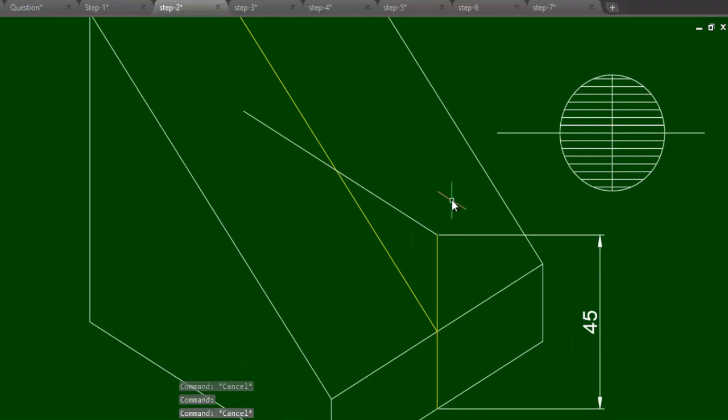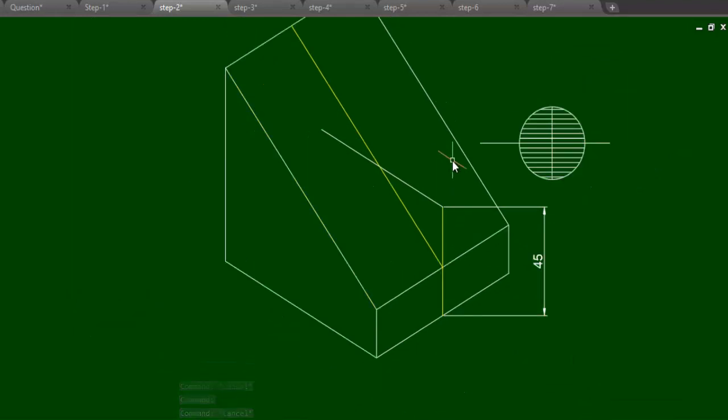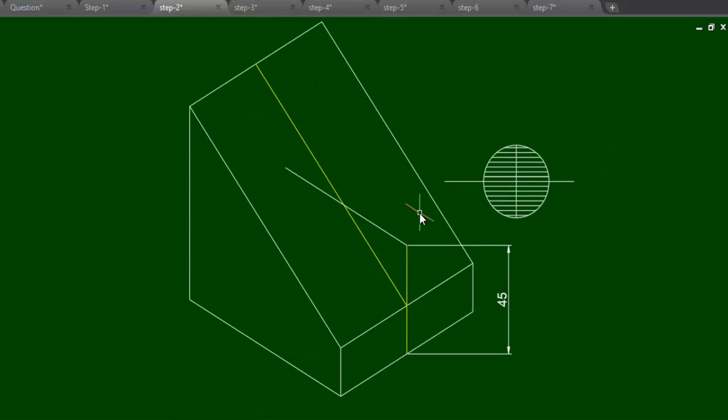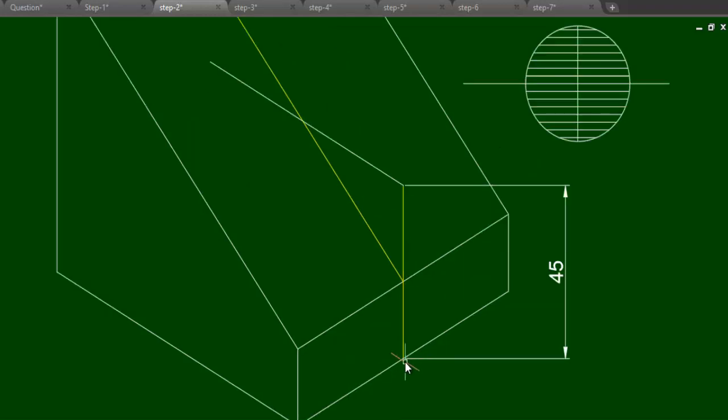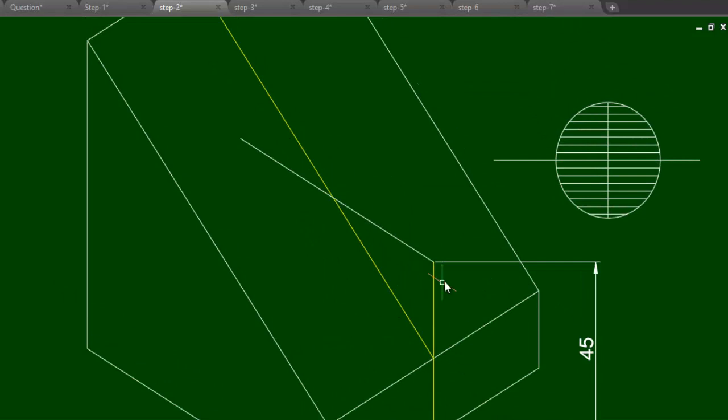Now in this step, you can take the drawing instruments and a sketchbook and create this particular diagram. Whatever I am explaining, you can pause this video and create those steps, right? So from here you create one line of 45 millimeter. Why 45? Just as I told, because it is lying at a distance of 45 millimeter from the base. Then from this point you draw one line.